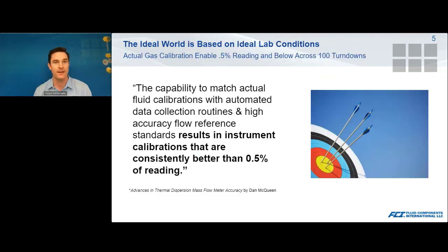So one of the foundational things I'd like to get across here is that the accuracy ratings that you read about in product literature, in the data sheets, on the websites, and the marketing materials, in this case on the screen, we have a white paper. Those are all based on ideal lab conditions, meaning that you have clean, dry gas, plenty of straight run. It's in a lab, which could be very different than the real world nitty-gritty applications that we see in the field.